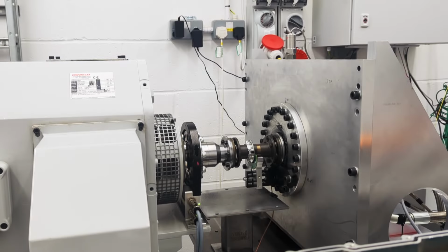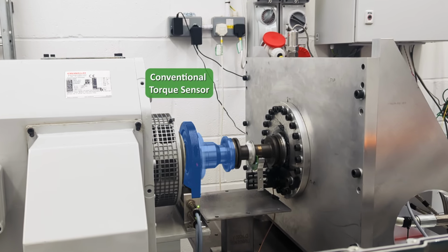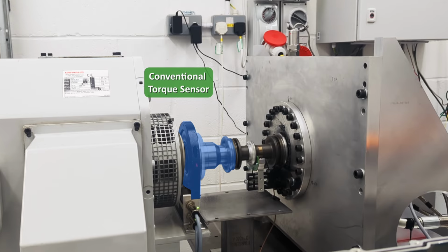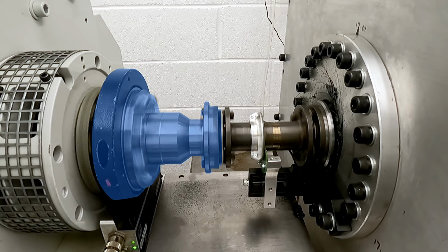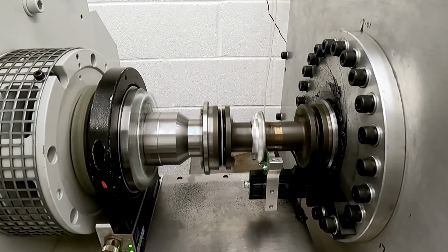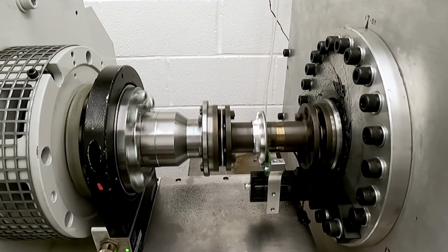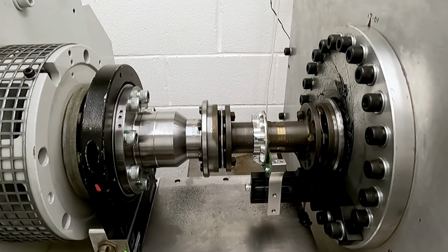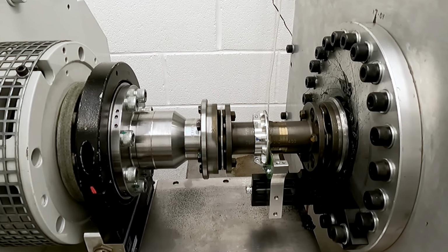But there are challenges to implementing torque sensing in electric motors. Normal torque sensors are commonly used in dyno testing, but they are too big and too costly to be included in a powertrain system. As well as needing maintenance and being susceptible to electromagnetic radiation and DC magnetic fields, measuring output torque in a production motor system is very difficult, and not something that most engineers even consider in the development process due to these issues.